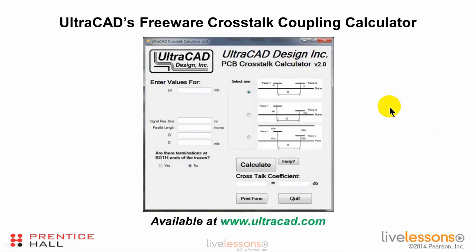UltraCAD has a freeware calculator that will estimate the crosstalk coupling coefficient. In my experience in using this calculator, it's pretty good for a microstrip environment. There are so many variables in a stripline environment that it tends to overstate the crosstalk coupling in a stripline environment. But H is the height above the plane.